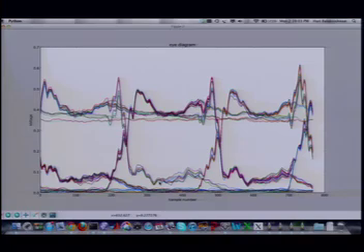Does this look like it's very linear? Would linearity be a good assumption for this channel? This is very partial information, but does it give you enough to judge? So why do you think linearity might be good here? Were you saying yes, it's a good assumption? Yeah, because time doesn't matter. Because what? If you have a signal go 5 seconds on a different signal, it'll still appear the same. But that's the time invariance argument that you're giving me. What's a linearity argument? Yeah? When you scale the input, the output gets scaled accordingly.